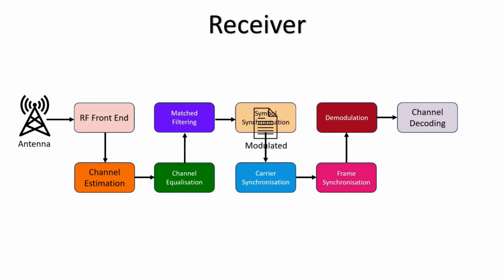Next, the frequency offset between the transmitter and the receiver will be synchronized, and based on the header in the data stream, the correct frame is identified. Finally, the signal is demodulated and decoded for errors, and the valid data will be fully recovered and ready to be transmitted to the next layer.